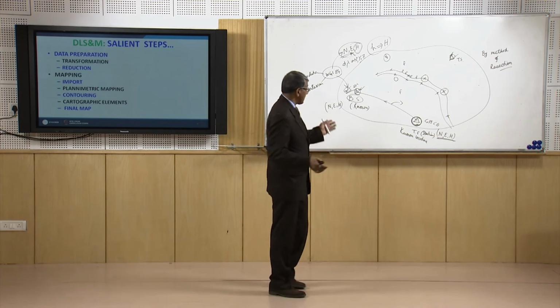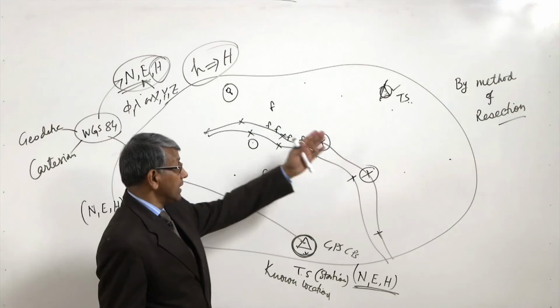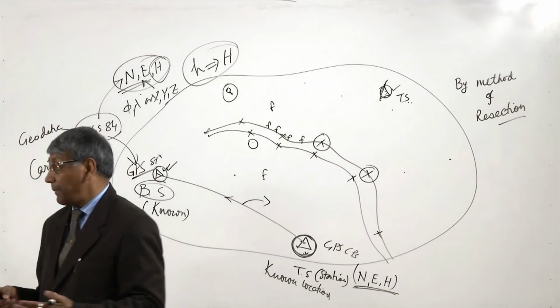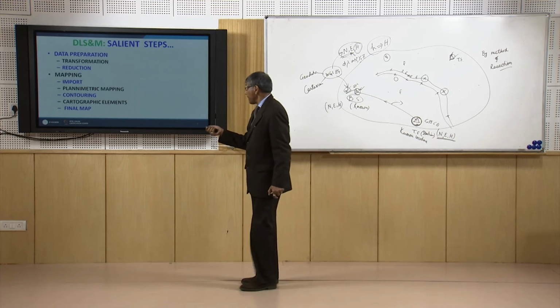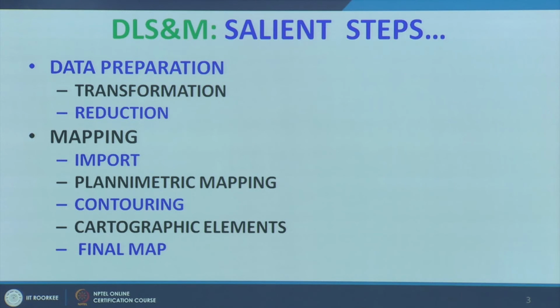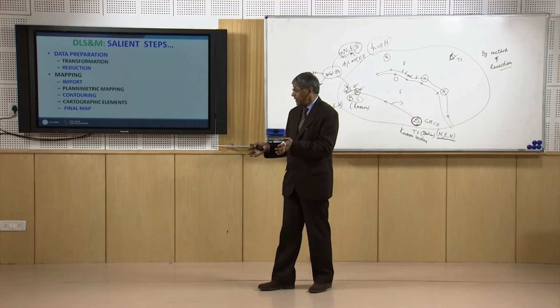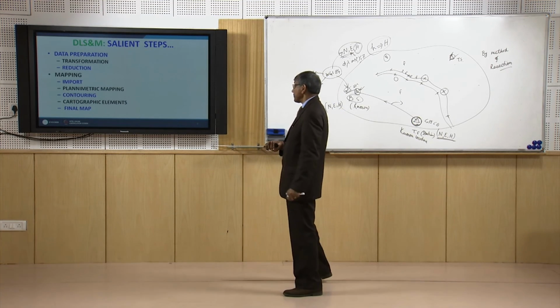All the points will be taken care of, the planimetric position as well as the feature. In planimetric mapping, the software will take care of the planimetric position like northing and easting, and the feature like road corner, tree or building corner, and accordingly it will be depicted in the map.